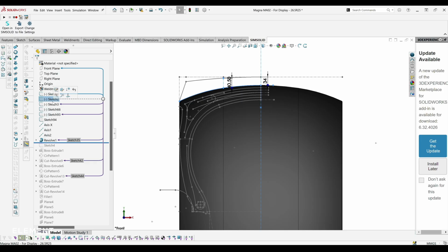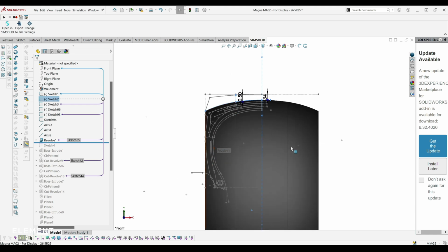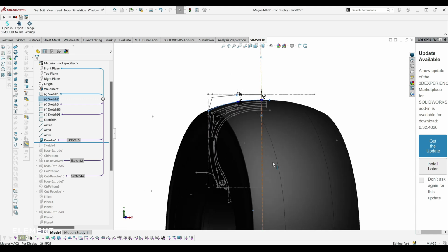This is a radial tyre, which basically has steel casing wires that go across the tyre and go around the bead. You can see down the bottom there. We're modelling in the rim and the flange of the rim, the bead and the casing wires that go up and around the bead and how they're going to interfere on the bead. Then we model in the other radial plies, which basically hold the air pressure in place. And then we even model in the different rubber compounds within the structure.